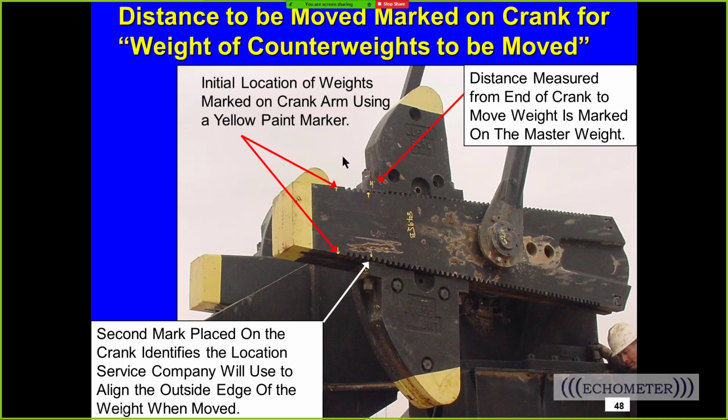Put a mark on your crank so you can see where they were and where they're supposed to be. And when you come to this well next time, you can see that the weights have been moved to balance position. For me, it's a good technique to mark, as the mark will stay until they paint the unit probably. And some wells they don't paint them for a long time, so you can see that they're probably imbalanced just by looking at these marks.